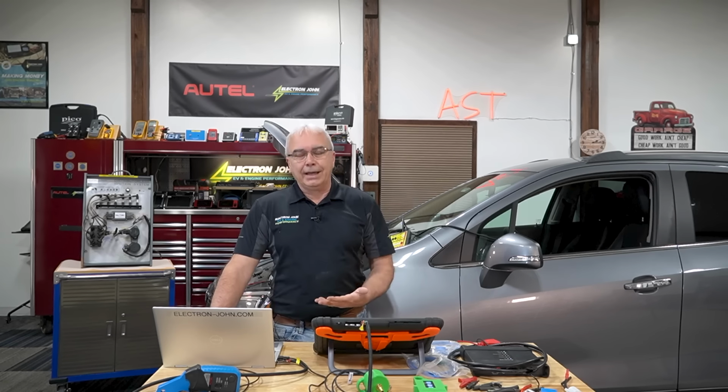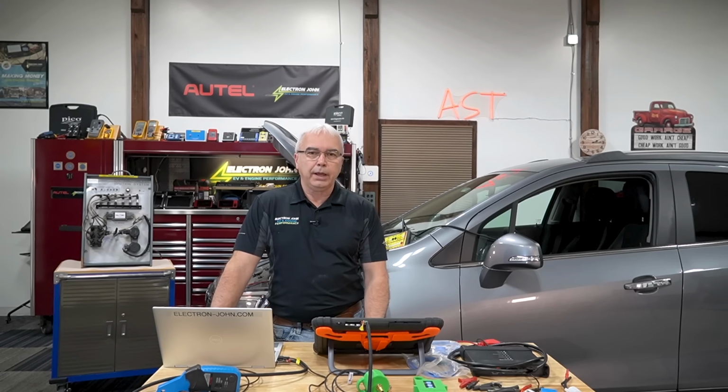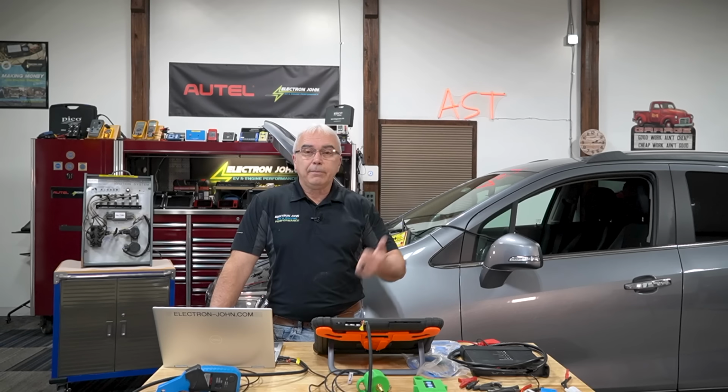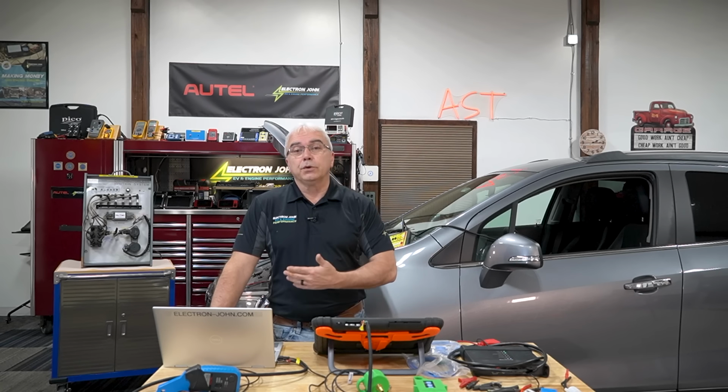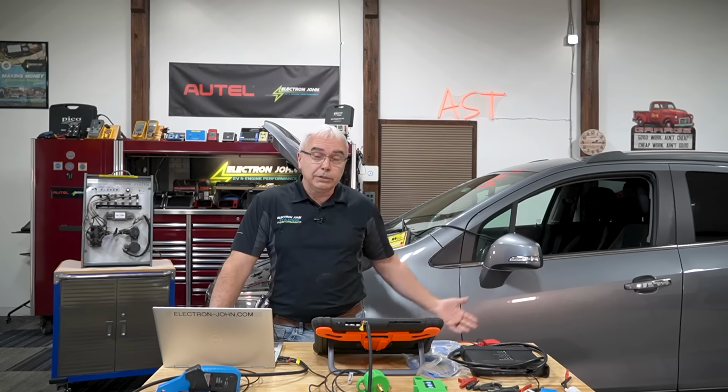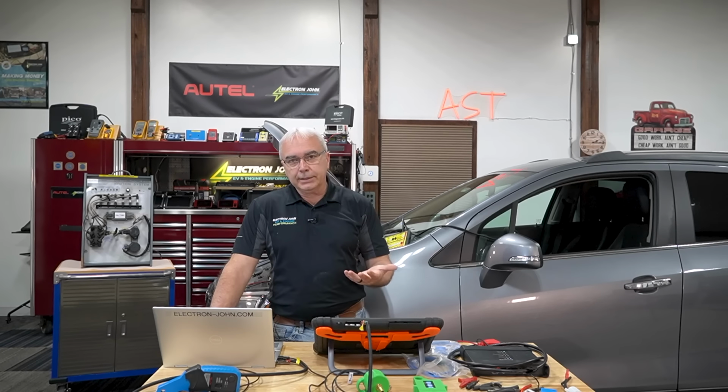Well, if I'm still alive and I'm still actually able to comprehend what I'm doing on my scan tool, it can't be 180 degrees. I get it, there's under hood temperatures, and maybe if you're in the desert, but realistically, that's an extremely high intake air temperature reading, and if it's higher, then obviously everything follows suit. So where's it getting that extra temperature from? It's getting it because hot exhaust gases, which could be 600-700 degrees Fahrenheit, can't make their way out the tailpipe, so it's finding its next hole. In this case, it happens to be the throttle plates, which is how we're increasing that intake air temperature sensor value.